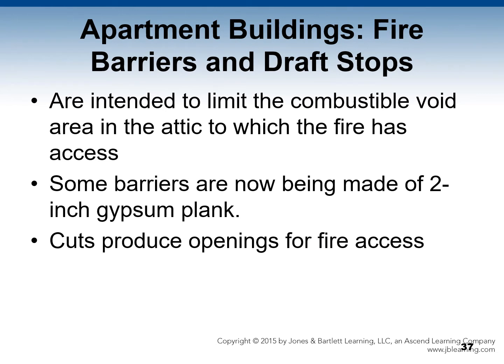With fire barriers and draft stops, these are intended to limit the combustible void area in the attic to which fire has access. Plywood or chipboard is used for the draft stop. Some barriers are now being made of 2-inch gypsum plank. They are cut in the field to meet the slope of the roof. These cuts produce openings for fire access.